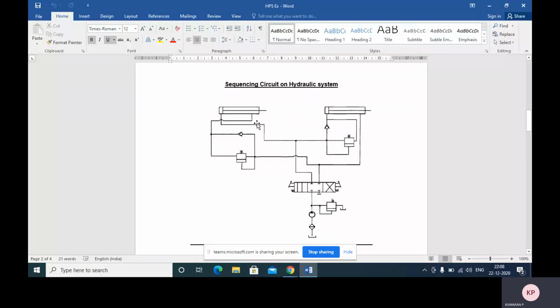So due to this negative pressure, it will come back through the same way and the pressure will increase in this sequencing valve. So what happened due to this pilot line, this will push the spring up so that the sequencing valve will open now. Same time, fluid back pressure is going to this check valve also. It is already in the opposite position, closed position. So fluid will not flow in this opposite direction.